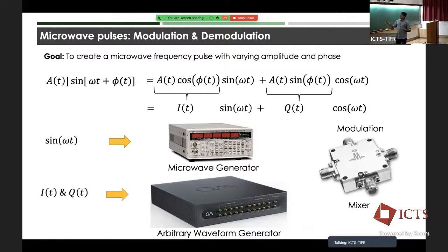So those are model dependent, how much price you're willing to pay for that, and how much accuracy you want in this operation. So this is the ideal thing you actually want. In reality, it doesn't do exactly this. I'm not going to go into that today at all. But just to give a quick hint, it turns out that it's not able to keep sine and cos exactly, so their phase is not exactly 90-degree different. When I becomes 0 and Q becomes 0, ideally you want the output to be 0. That doesn't happen. There's always a little bit of signal bleeding through. So you have to do various calibrations to make it work as close as possible to this. These are very old technology. It's been around from World War II days, I guess, for use for radars and other things.